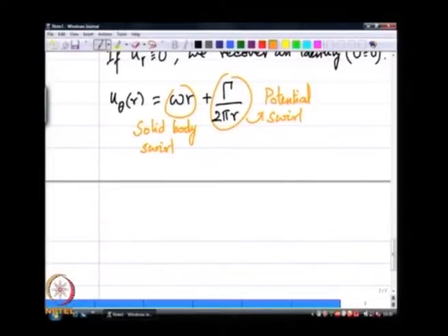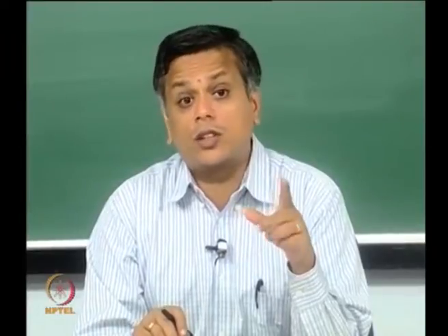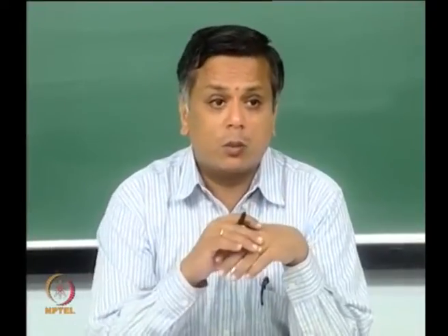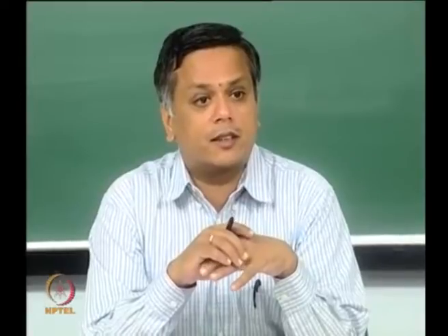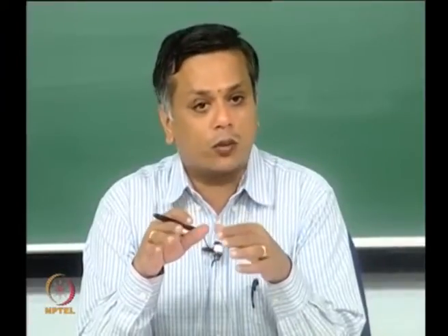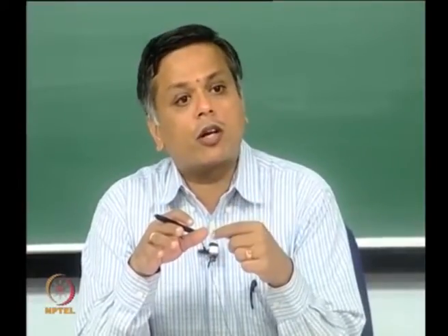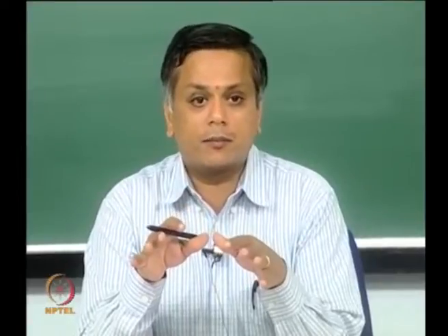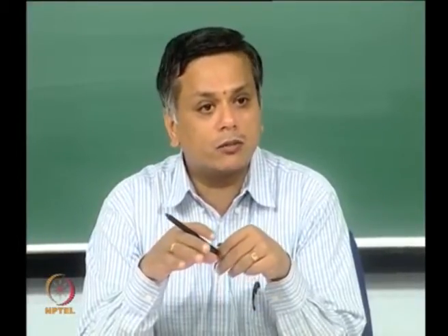If you look at any kind of swirling flow, remember that we are not restricted to one of these two forms, except in the case of a viscous flow. We will look at that later on, but as far as inviscid theory is concerned, the only thing that you are allowed to conclude is that if you tell me what V theta as a function of r is, there is a corresponding pressure field associated with it that can be calculated from the radial momentum equation.